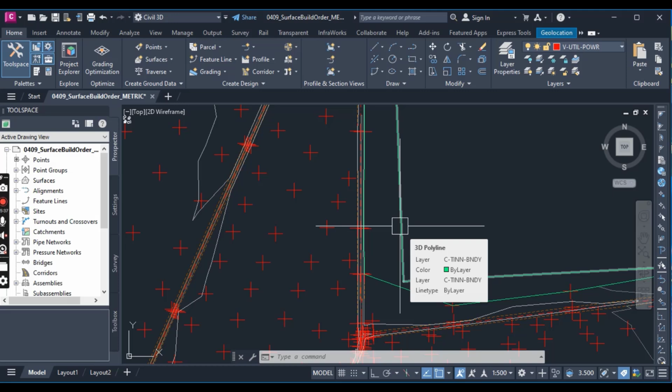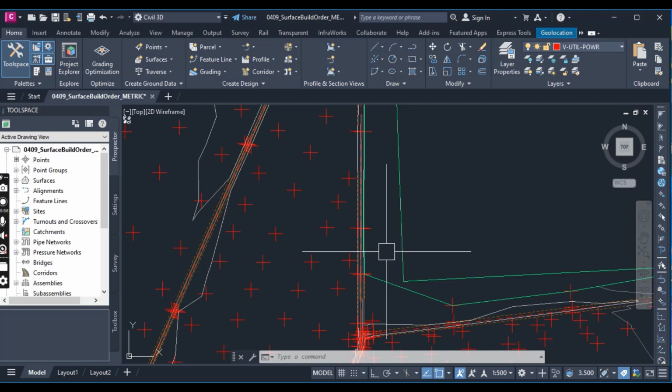If you would like to see what the surface would look like without a particular operation, you can clear the checkbox next to its listing in the definition tab. You can completely remove operations from the list by right clicking the items in the list and selecting remove from the definition.